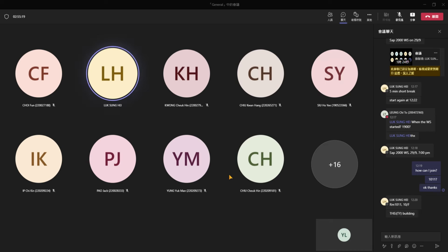You can also assign code numbers arbitrarily without following the suggestions in the notes. I showed you a similar thing in tutorial 1. You can assign code numbers in other orders. I always encourage students to redo the examples in the notes by changing the member orientation, by changing the code number orders. On one hand, it practices the skill of the stiffness method. On the other hand, it also helps you to understand how to arrange code numbers.